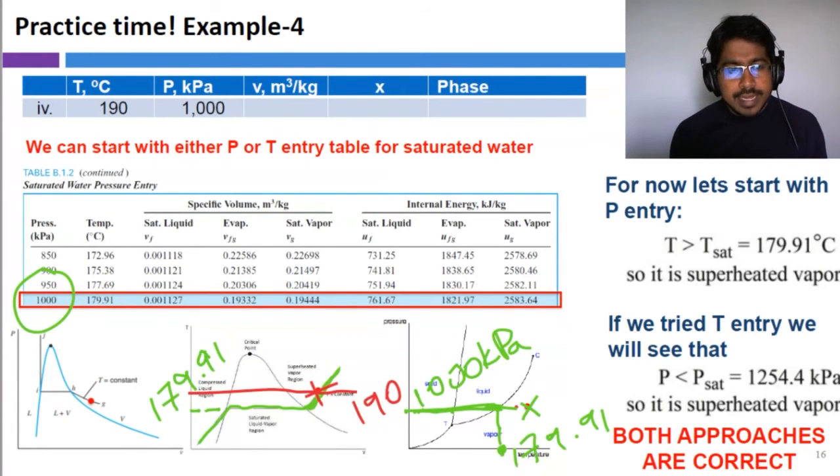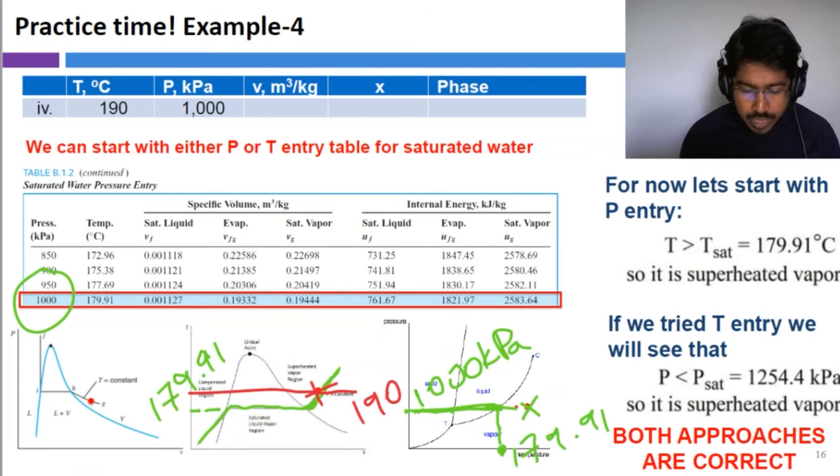It is not the ones that determine what the pressures and temperatures on the table are. We have to compare our values with the table just to confirm whether our state is inside the superheated vapor, liquid plus vapor, or compressed liquid region. So are we clear on that one? That is what we did in PT. Now let's start identifying the same with the PV diagram, right?